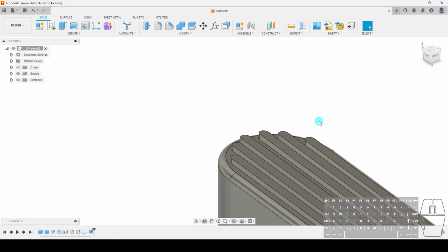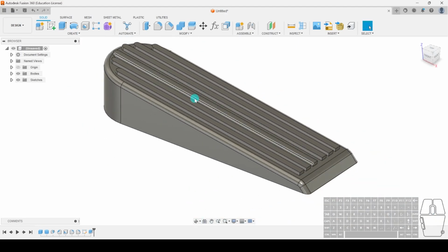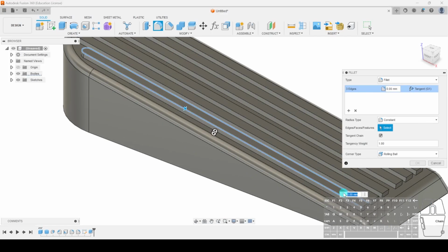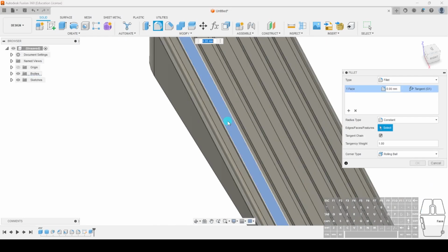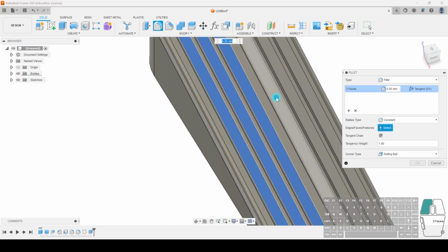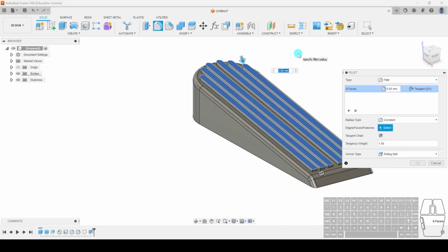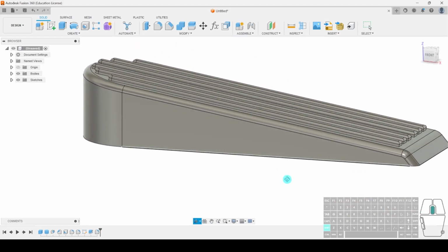So hit Finish Sketch, it looks okay. It looks better now. We're just going to end this off by filleting the edges. Now I can select the edges individually one by one, or in this case, since I want it to be all even, I can simply select the face. So I'll select the first one, second, third, fourth, fifth, and the sixth. So now if I give it a fillet of say 1mm, it will automatically do it along the edges, like so, as you can see.